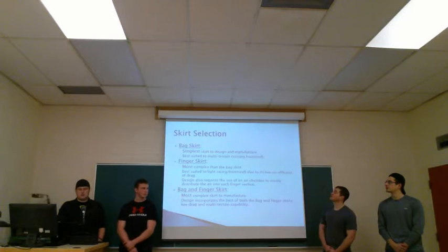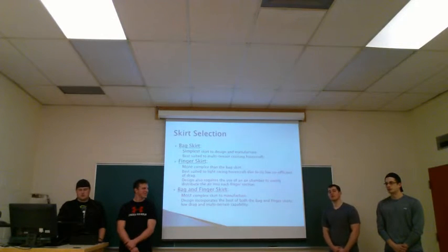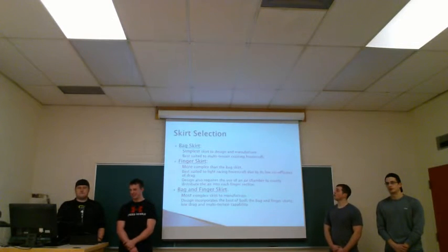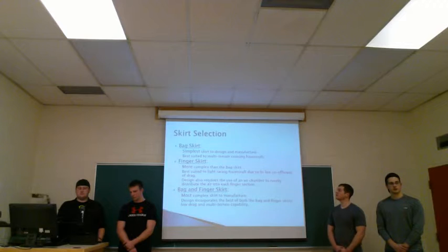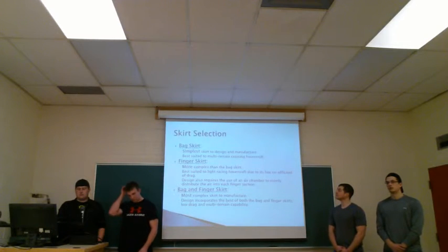Another section of the hovercraft that we had to choose for is our skirt. We had 3 choices: a bag skirt, a finger skirt, and a combination of both. The bag skirt is the simplest design, both design and manufacture, and it's the best suited for multi-terrain.